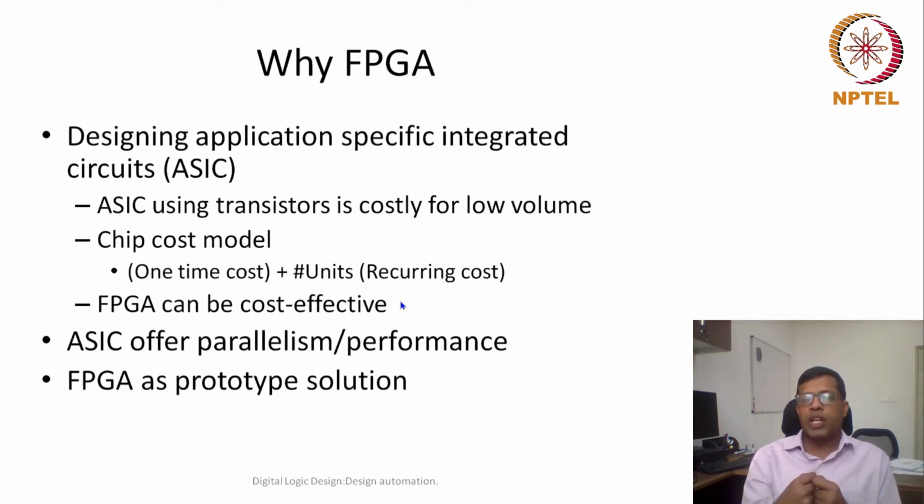Whenever you would like to come up with a new hardware design, rather than going for a direct transistor based design, many people go for an FPGA solution so that they can at least prove to, let's say, a funding agency that this idea works. Because the volume is low, you would only need a couple of units to show that this idea works.